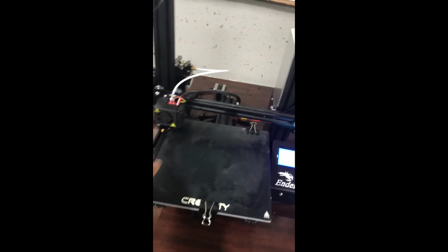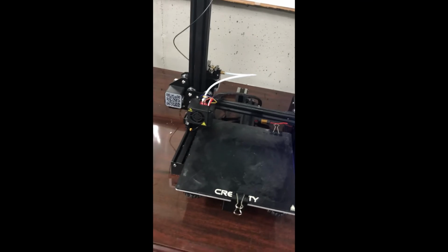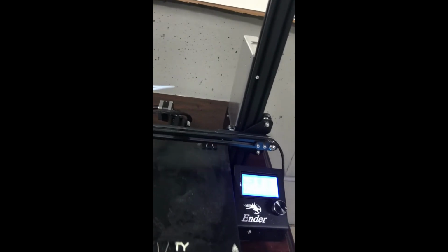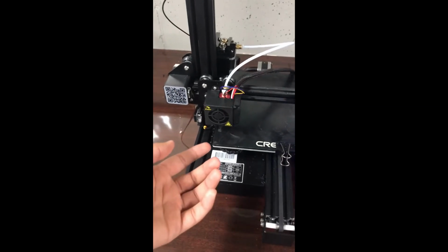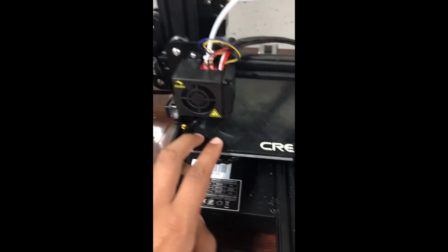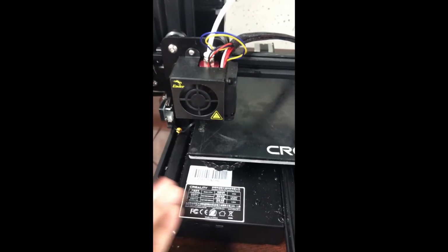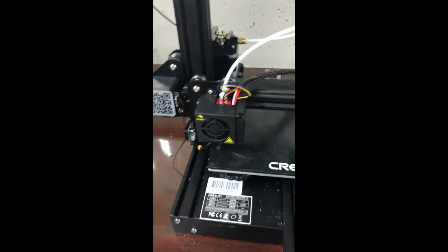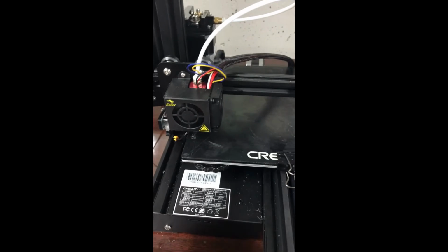And another thing you can do is make sure that when you're 3D printing, your bed is level. Some 3D printers auto level their beds. This one doesn't. So what you do is there are small wheels under here that you turn on each of the 4 corners. What you can do is put your nozzle right above each corner. Take some sort of paper like an index card, or you can use a dollar bill. You do this while it's turned off. Put it right up against the printer. Go as low as you can with the nozzle, and then just adjust it so the nozzle is barely above the bed and the dollar bill or the index card barely goes through. Do that for each corner and the middle.